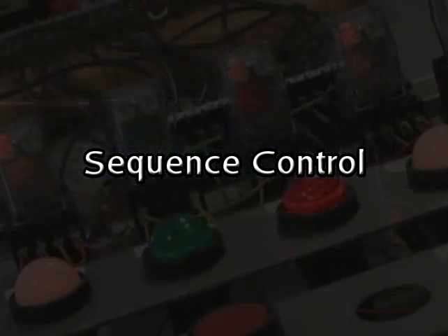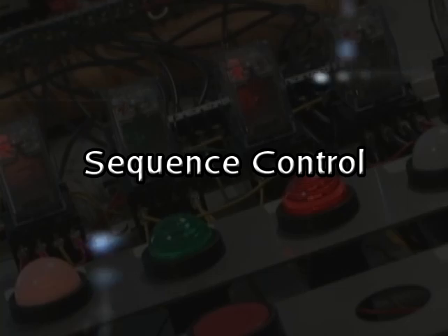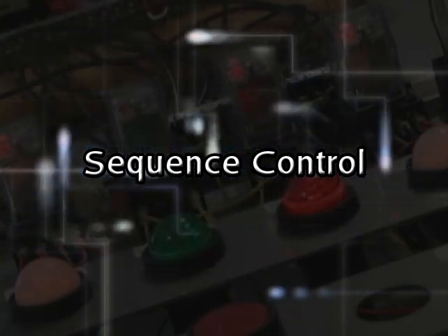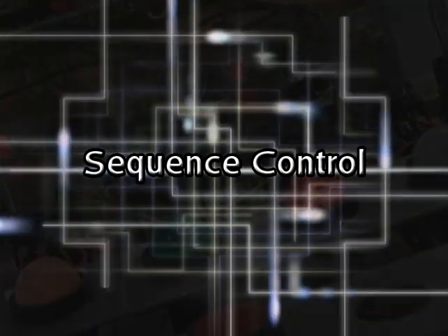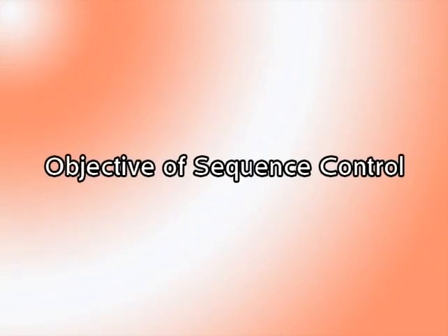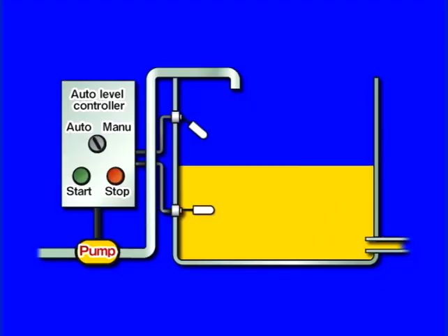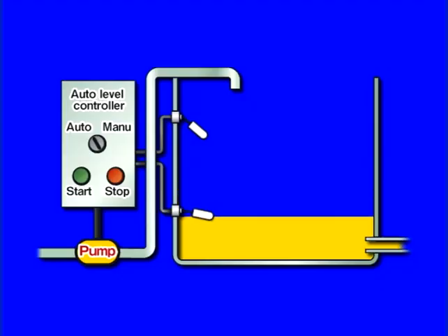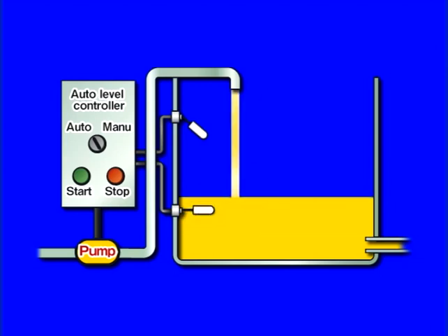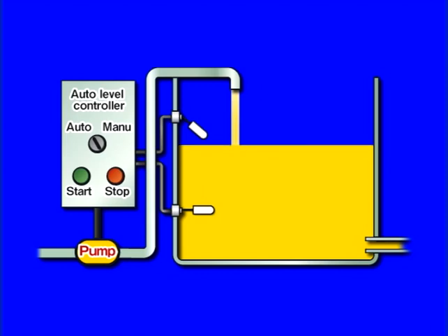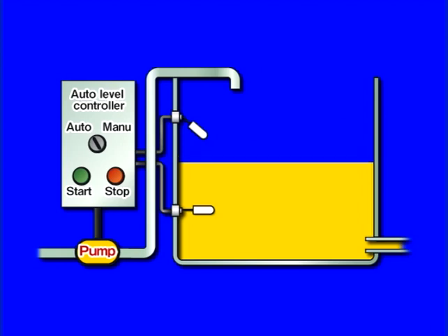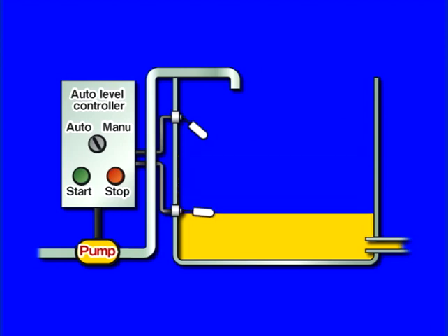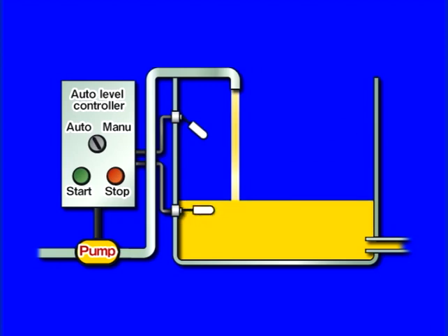The mechanism by which a machine is operated step by step in accordance with prescribed procedures is known as sequence control. Many pieces of equipment operated automatically using sequence control can be found on board ships. As a simple example, there is a sequence circuit to automatically supply fuel oil to a settling tank by a fuel oil transfer pump. This sequence circuit controls the fuel oil transfer pump, stopping the pump before the fuel oil in the tank overflows, and resuming pump operation as the level of oil in the tank drops below a preset level.